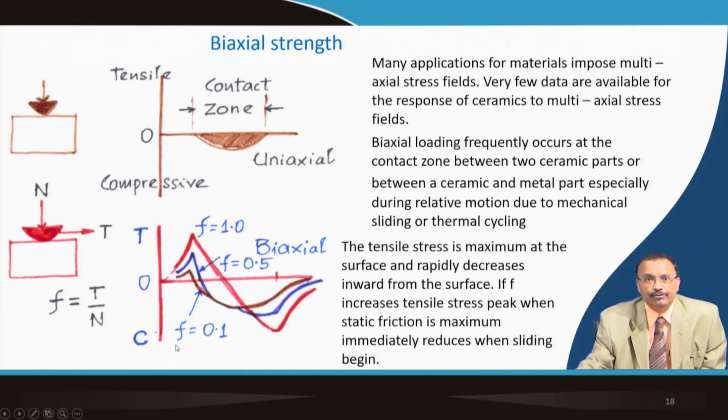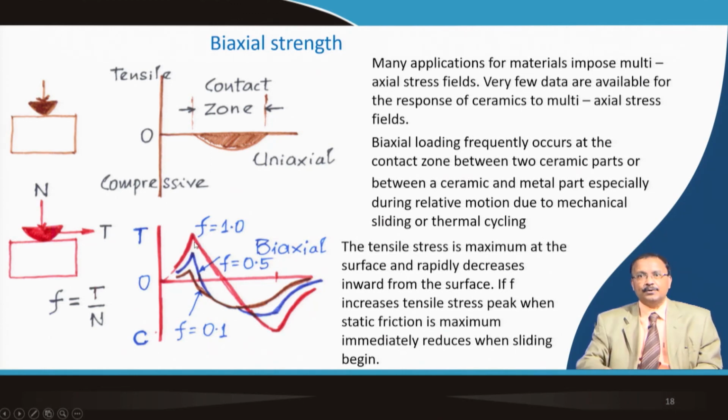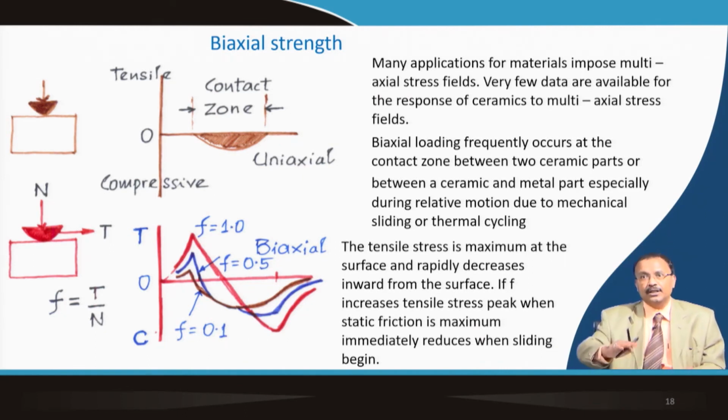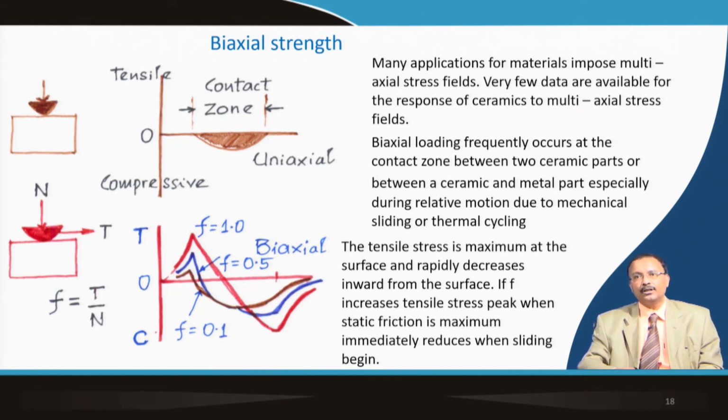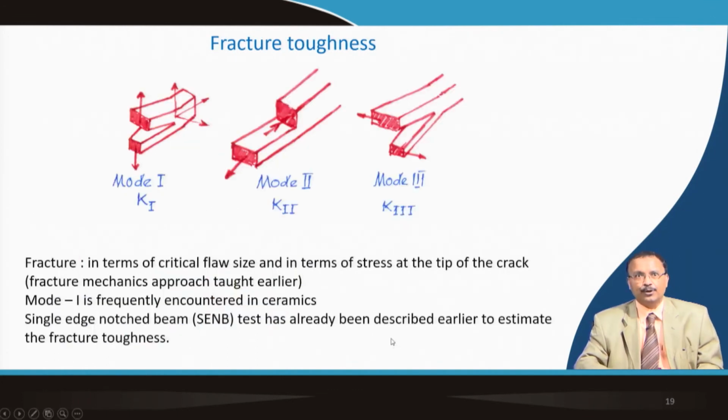If the value of F increases, then the tensile stress also peaks when the static friction is maximum, and then it immediately reduces on sliding. Due to this fact, the chipping etc. occurs, and when I talk about the machining of ceramics, you will see that this is particularly important when the machining is done at the final stage of ceramic fabrication, and the effect of the biaxial strength is elaborated at that point.